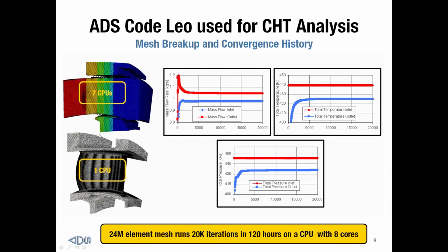And the reason for that is that, if you recall, the fluid and solid pieces have roughly the same number of elements. The solid piece is only solving one linear equation, whereas the fluid pieces are solving 7 nonlinear equations. So even though this is broken up and this is much larger, this solid piece ends up running much faster than the fluid piece. So there's really no reason to break up the solid.